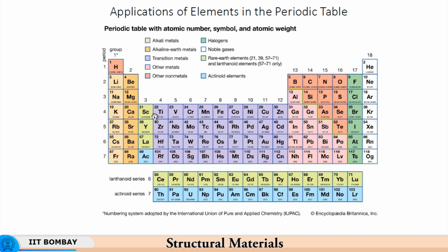So, the selection of this material depends upon the strength to weight ratio. In a structural material, the strength to weight ratio is an extremely important parameter as far as application goes. And different sectors use different kinds of materials for their application. For example, copper would be used in the electrical and electronic industries. Copper is extensively used there for its electrical conductivity. Now, electrical conductivity is not structural, so it is more of a functional material as far as electrical industries go.